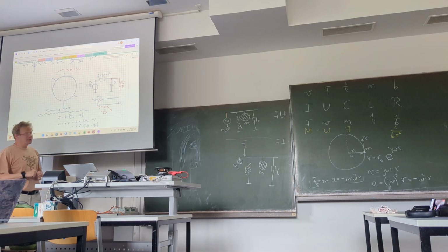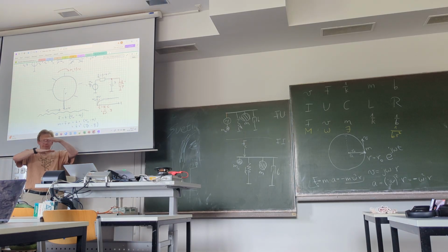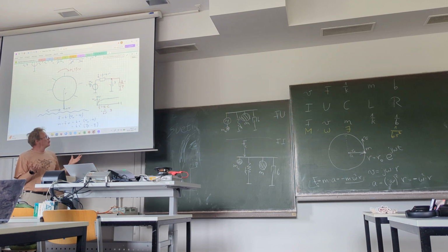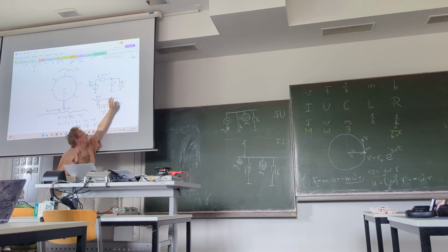You can say they are just disconnected, the wire is disconnected, and inductivity would be a short circuit. Okay, so in this case, this capacitor does not play any role anymore after a long, long time. You can just neglect it.